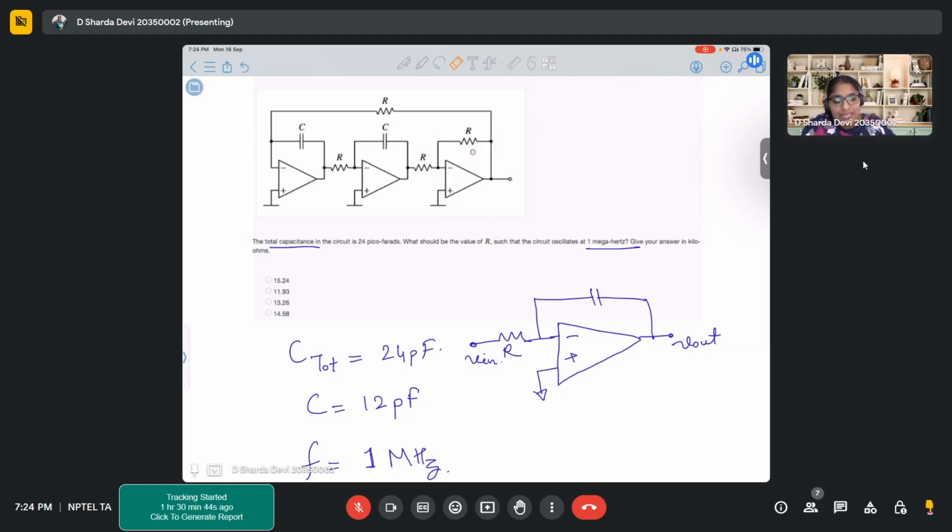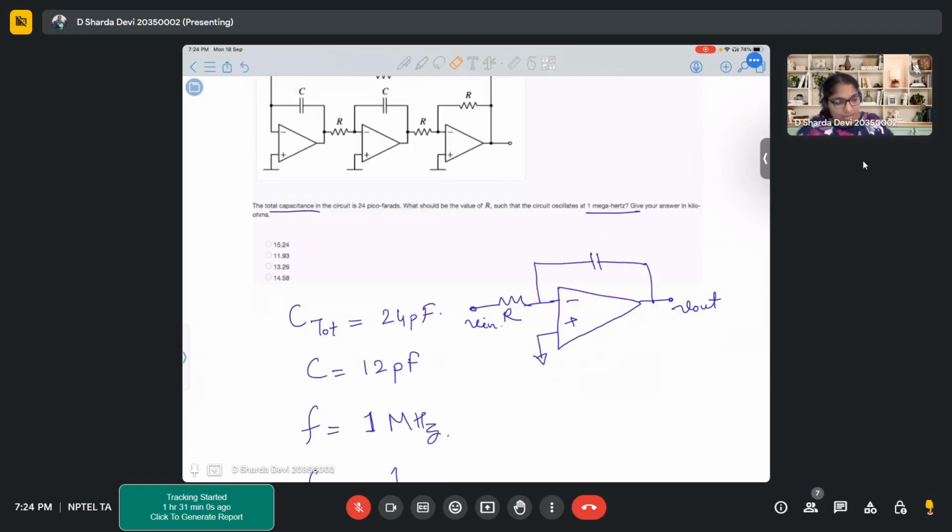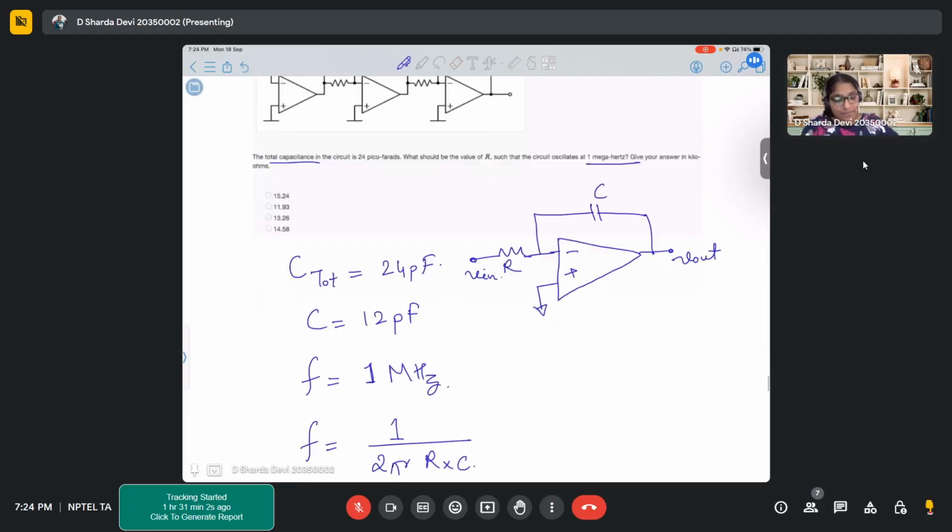Now looking at these two, these are similar structures, right? There is a resistor in feedback with a capacitor. Here also a resistor in feedback with a capacitor. So the basic circuit is a resistor and capacitor circuit. Here it is Vn and here it is Vout. Now let's write KCL at this node. So (0 minus Vn) by R plus (0 minus Vout) by 1 upon Cs equals 0.